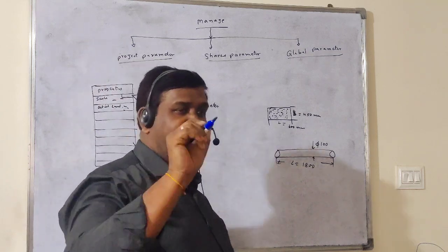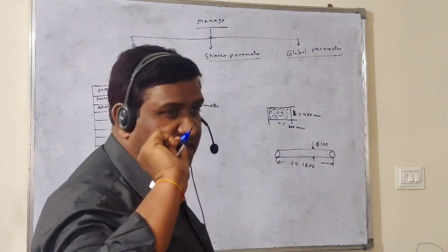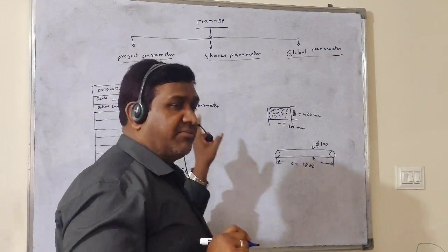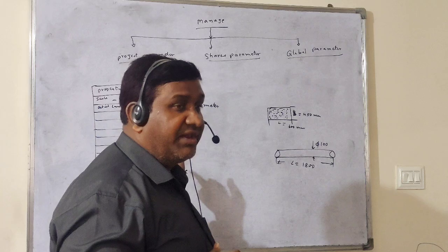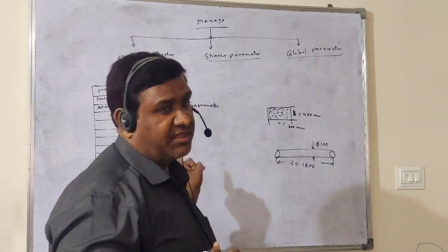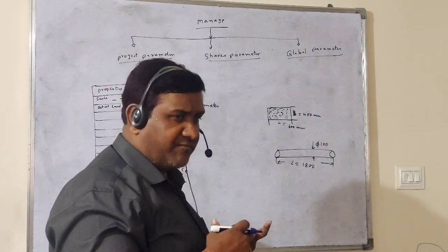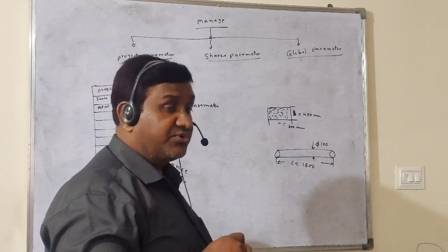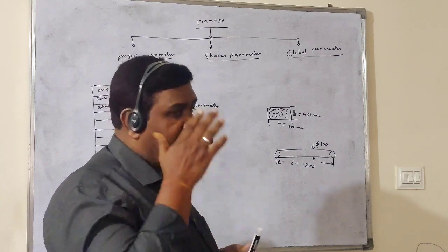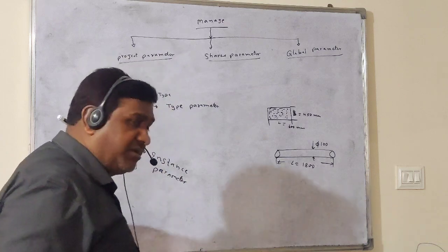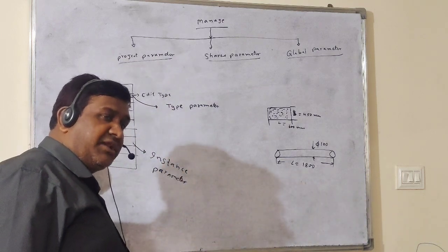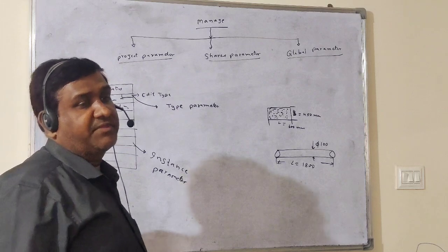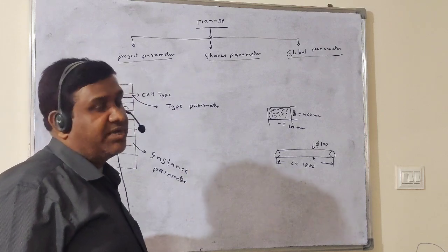If you click that pipe after making the model, automatically the properties toolbar should reflect its size, the width, the length, the diameter, everything. All information should be visible. Am I right? Some information may be visible directly in the properties toolbar, and some information may be visible in Edit Type, which is in the properties toolbar itself.